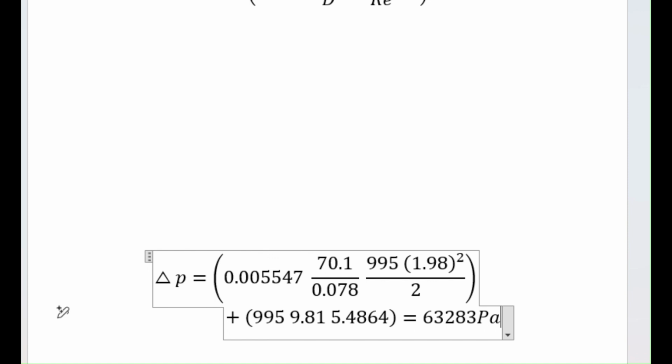And let's say if you have the local gauges in point A and point B, and you see that the pressure drop is higher than that, that means you do have a fouling issue. So you could maybe clean the pipe.